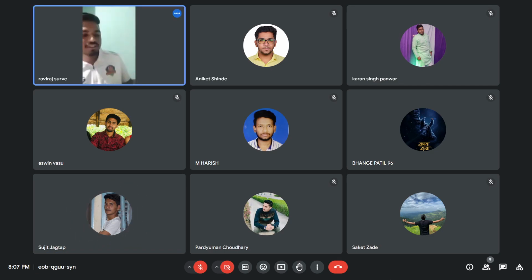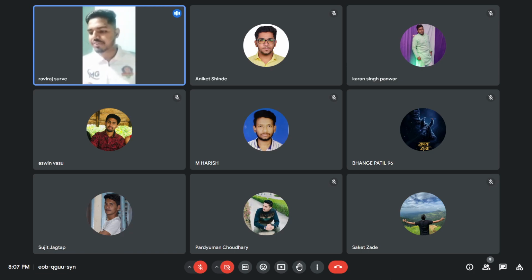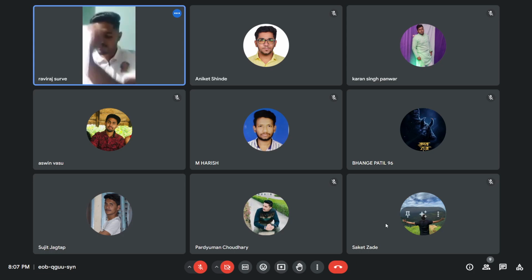Okay, no problem. So last question for you, Sujit. Tell me the types of compressors. The main types of compressor are rotodynamic compressor and positive displacement compressor. In rotodynamic there are two types: centrifugal compressor and axial compressor. And in positive there are two: reciprocating compressor and rotary compressor. Okay, so these are the types of compressors, right? Yes. Okay. Thank you, Sujit. Thank you, bro.